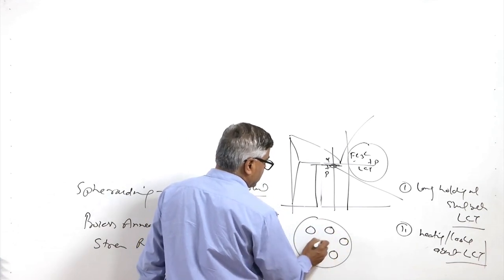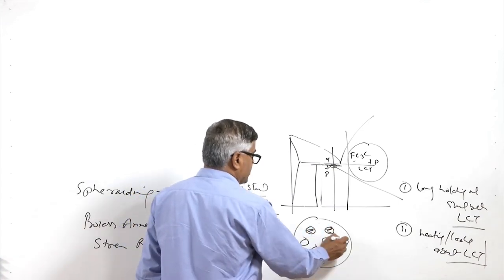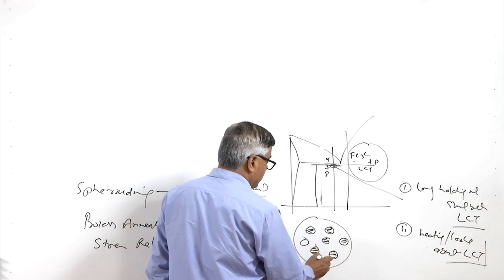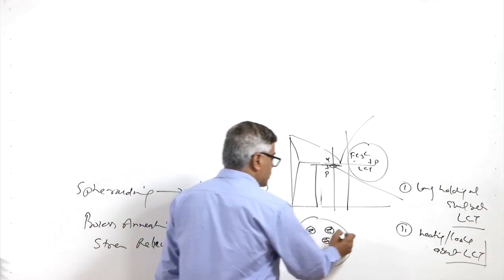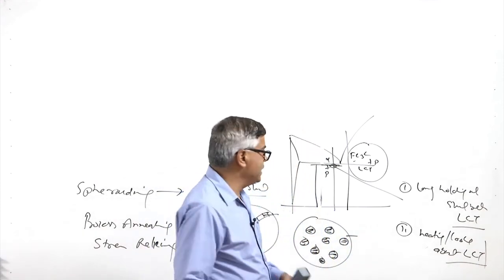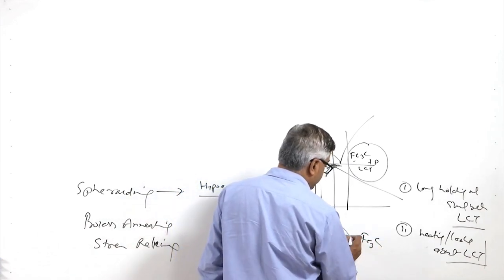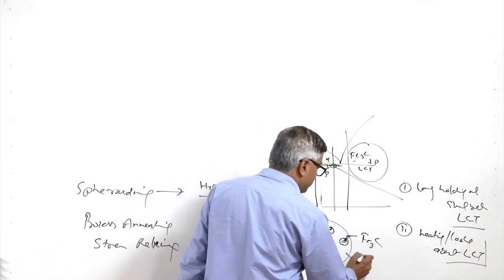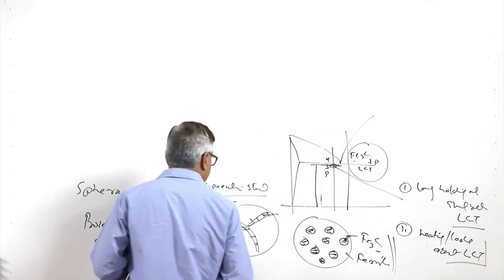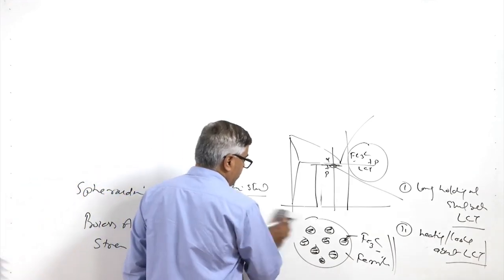So, the lamellas of Fe3C get spheroidized in the form of spherical balls, which allow easy machining. So, basically the embrittlement due to the Fe3C is reduced by the spheroidization of the Fe3C. So, these Fe3C particles and the remaining matrix is ferrite. This is what is achieved, and when it is done, it helps to realize the improvement in the machinability.